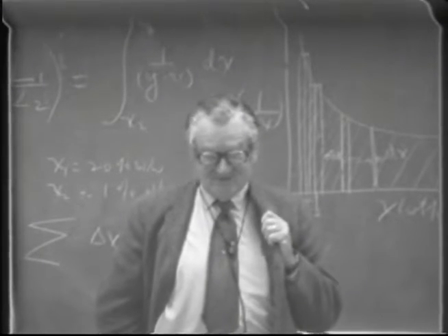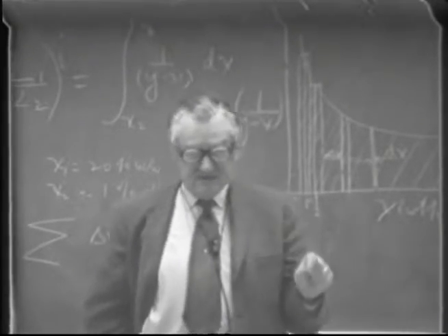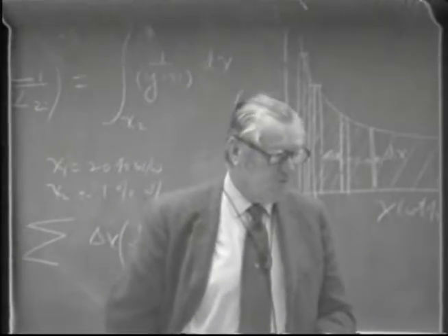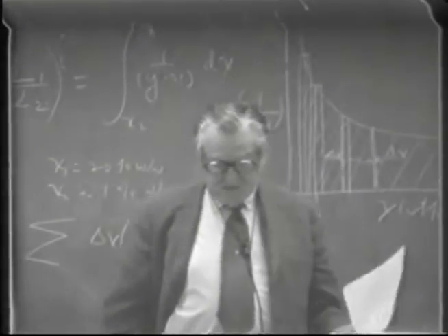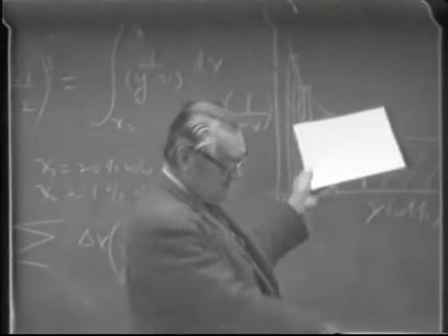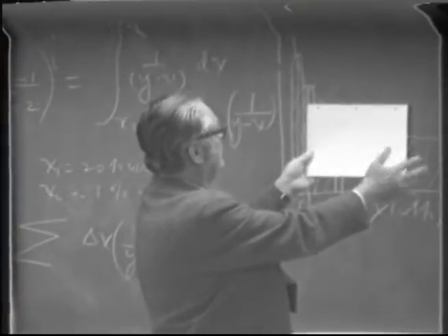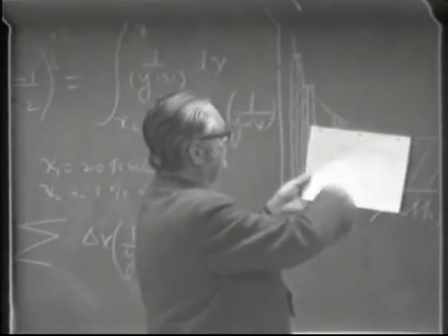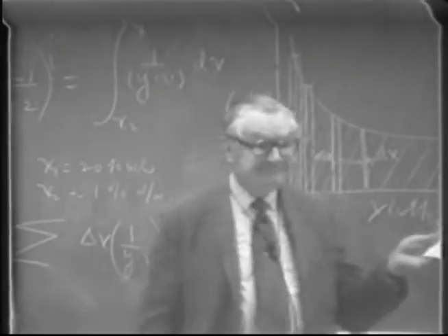Because if you're distilling at a low-proof spirit like beverage brandy strength, you will never get sufficient fusel oil to build up to cause separation by simple water dilution. So we're talking about the situations that would pertain when you have such conditions as illustrated by this table that I handed out also last time, where you have high concentrations of fusel oil accumulating on the plates.